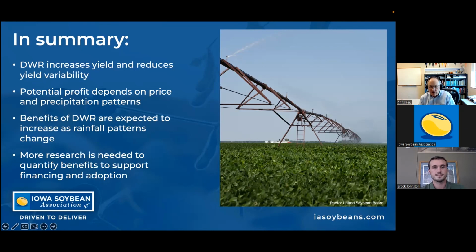So that's usually not a concern, but we want soil that can move water above that restrictive layer. So we don't want real heavy clays, or else the water won't move in between the tile lines. So that's what we would look for in a sub-irrigation site.